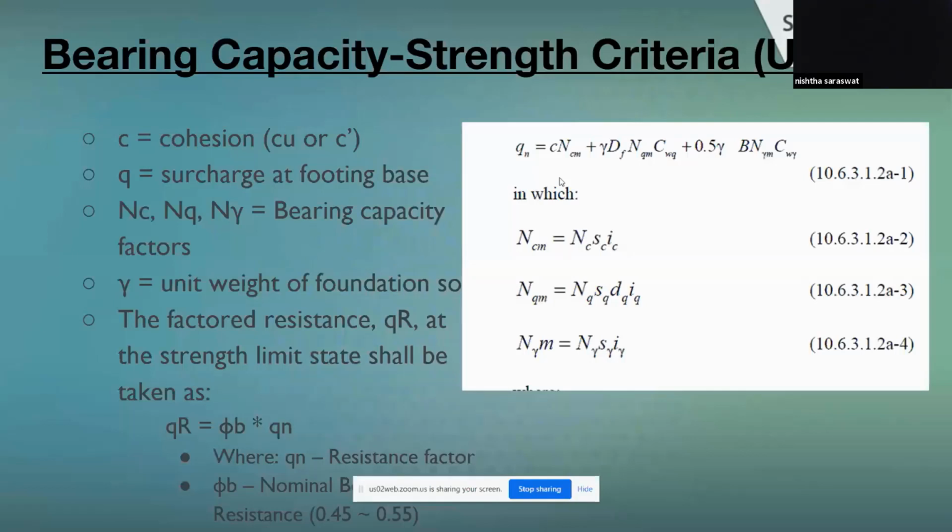And if you recall, the gradation of these soils is on the basis of the sieve analysis, for which the granular soils are typically the ones which pass through the 2 millimeter sieve, and the fine grained soils are ones which pass through the 0.05 millimeter sieve. And for organic soils, it has to be less than 0.002 millimeter. These are a couple of just benchmarks for this classification of soils.